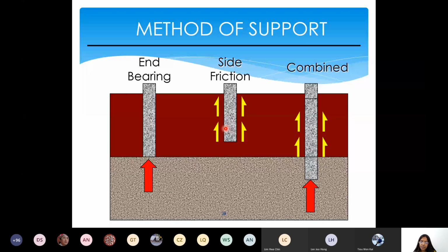The side friction will be either natural or artificial. They may also have some corrugation, like a corrugated steel pipe. Corrugated steel pipe will automatically have some perturbation, so that it will offer resistance to the movement of the soil, due to its property of friction. So it is either natural or artificial. They may have plastering artificially made, or chemicals used to create a frictional surface on the pile to resist the loading.